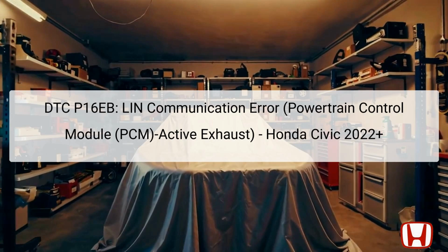Welcome to this troubleshooting guide focused on DTC P16EB, which indicates a LIN communication error connected to the Powertrain Control Module, PCM, concerning the active exhaust system in the Honda Civic models from 2022 onwards. The active exhaust system plays a vital role in managing exhaust sound levels and performance by utilizing actuators controlled by the PCM to open and close the exhaust valves based on driving conditions.